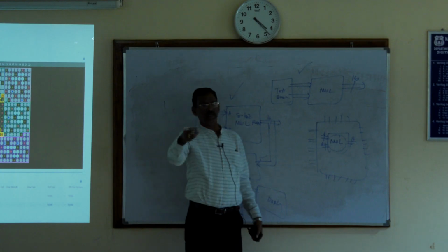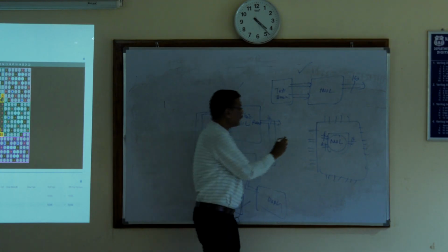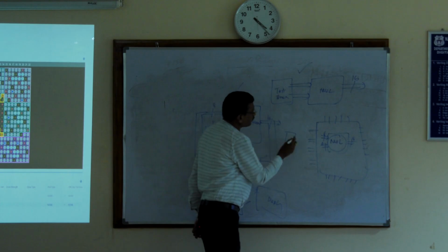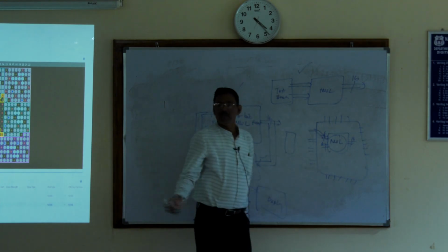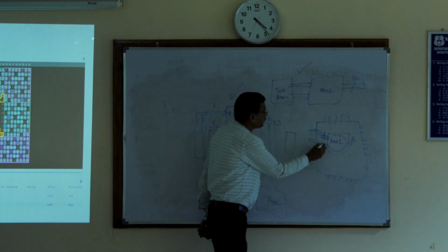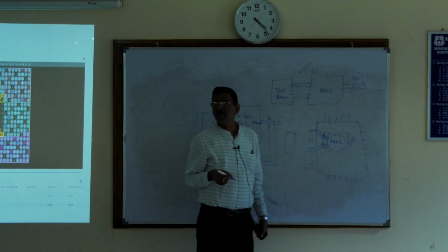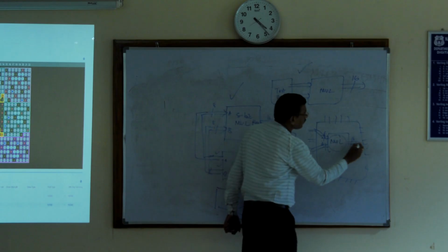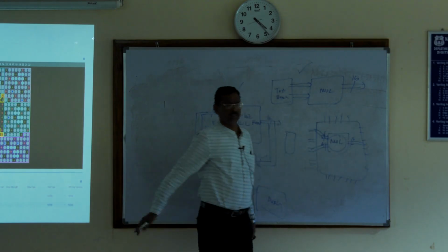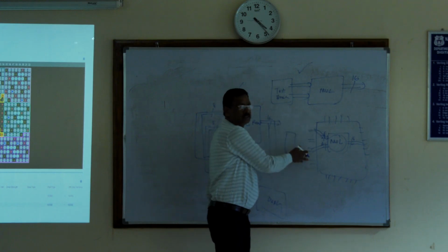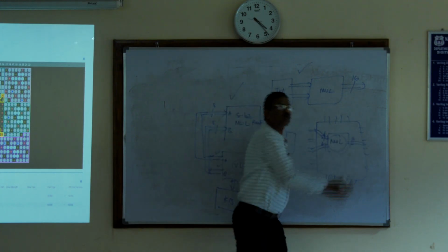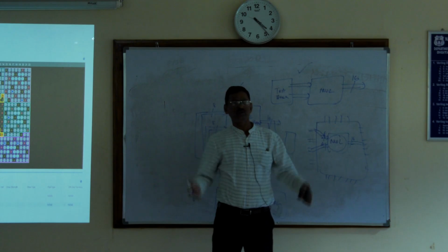If you want to test these inputs, you have to feed through some external input, maybe switches or any test generator logic. So this is the external input supply to connect. Then all these 8 pins you have to connect to FPGA port pins. Again, these 8 pins will be connected to 8 FPGA port pins. The 16 pins also you have to connect to 16 FPGA port pins. 32 pins are required. So 8 plus 8, 16, plus 16, 32 pins are used.